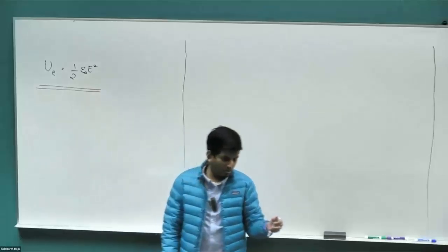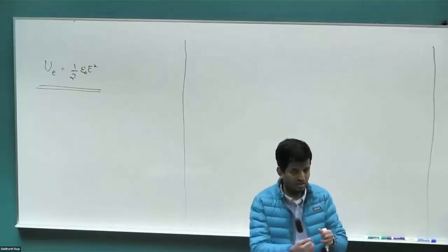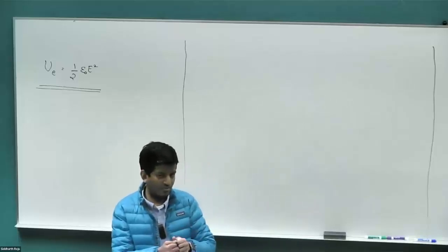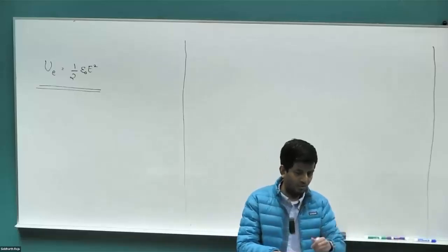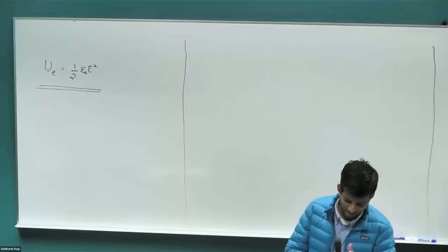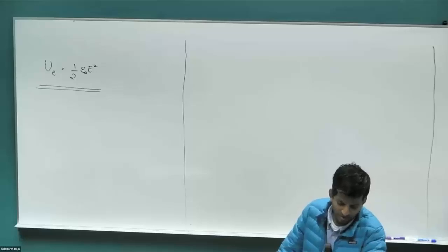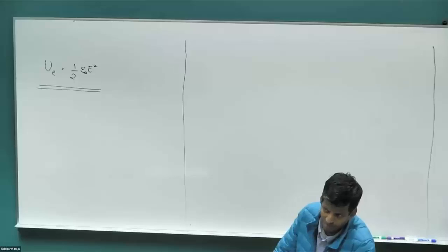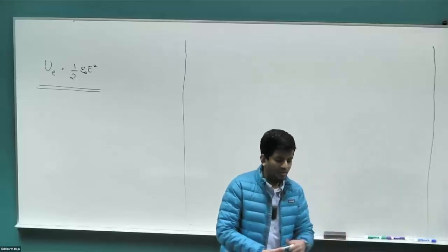And the way these motors work is there is a stationary part, and then there is a rotational part, and energy is transferred from the stationary part to the rotational part by some kind of air gap that separates them, right? And that separation is required because the mechanical isolation is needed so that one can rotate, one can remain stationary. And the term rotor and stator is somewhat rather arbitrary. If I hold on to the rotor and turn on this power supply, the stator is going to start rotating, right? Stator is just something that's supposed to be stationary, but if you operate it wrongly, even the stator can rotate. There is nothing special about stator or rotor.